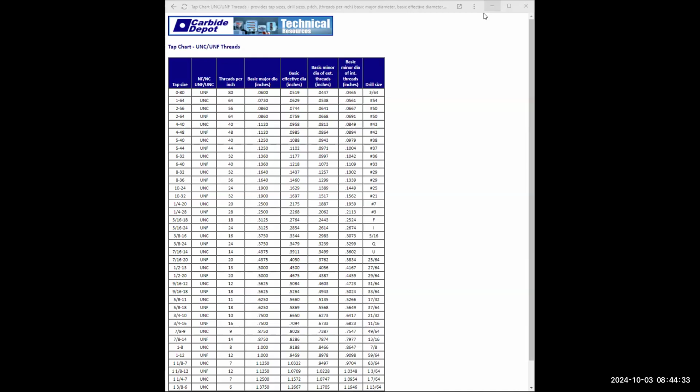We have to type an offset first. So let's type in offset. Oh, you know why? Because you're working at a different place. You're in the green area now. Draw a line here. You got that line 2 inches down. Now you draw a line 1 inch, 8 inch, 1 inch. Click, go down 1 inch, enter, go to the right 8 inches.